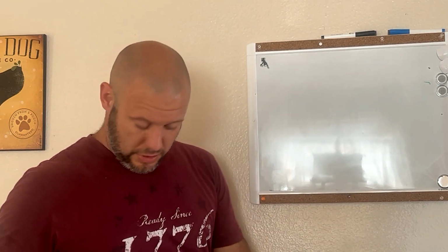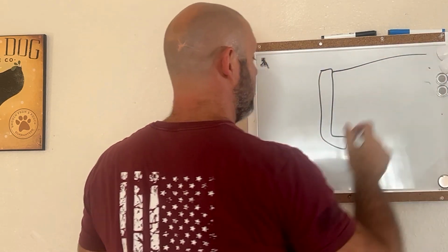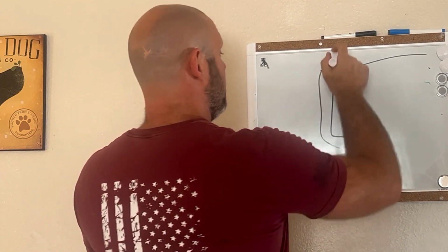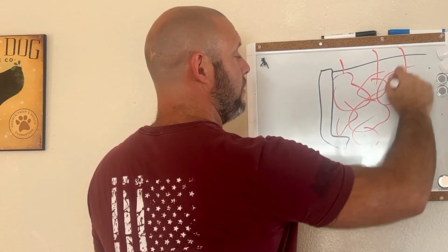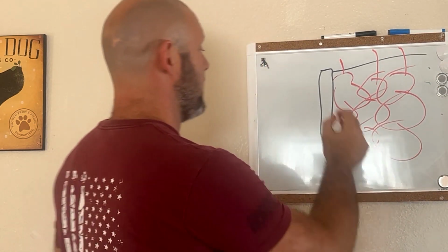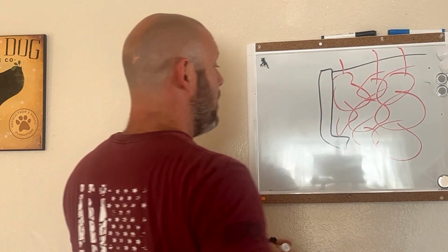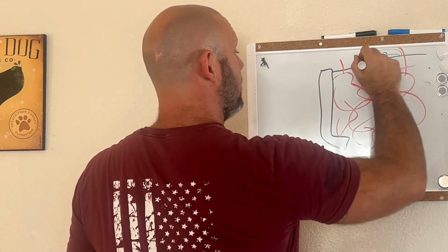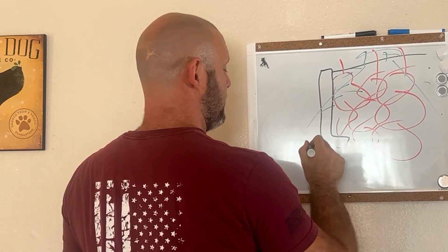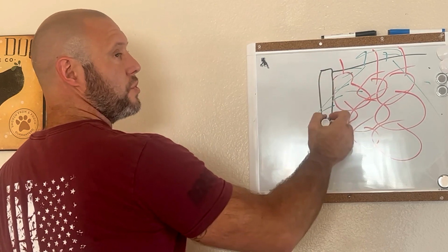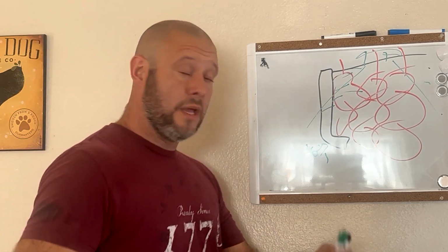Now, if I were to do a polymer injection, right? Hillside here, and then I do polymer injection underneath. What do we know about polymer? We know that it reduces lateral earth forces by approximately 40%, which takes some of that lateral pressure off of this, or any load that you have up here, right? If I've got a building, a structure, or anything up here that creates load down into the soil, it reduces that lateral earth pressure by approximately 40%. And if that helps take the pressure off of this retaining wall, reduces the lateral forces that are creating the overturning, then it's all good, right?